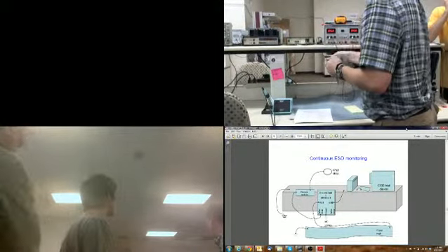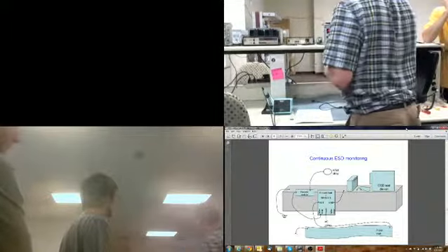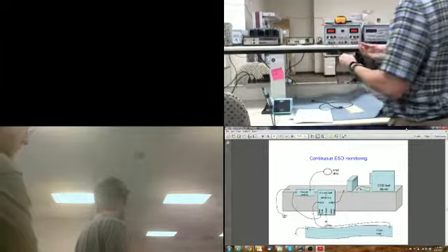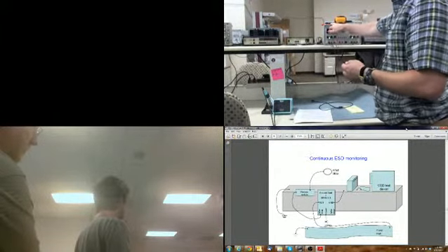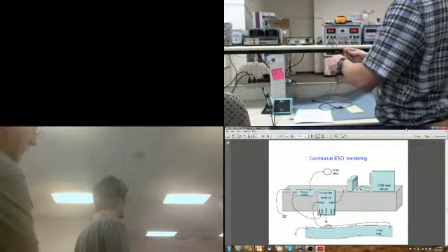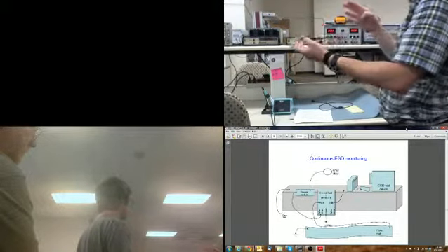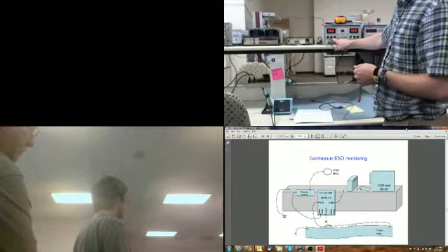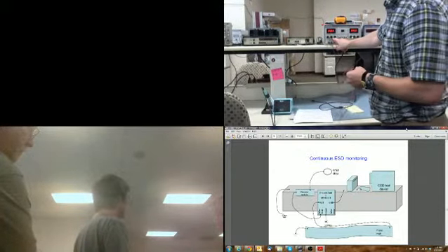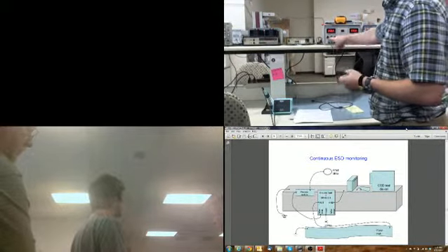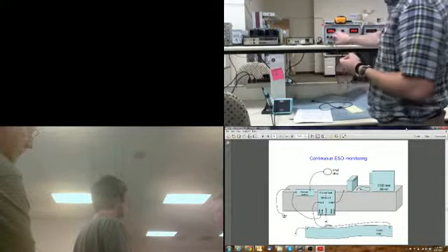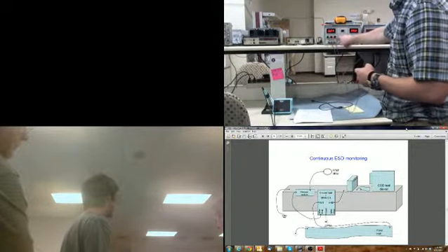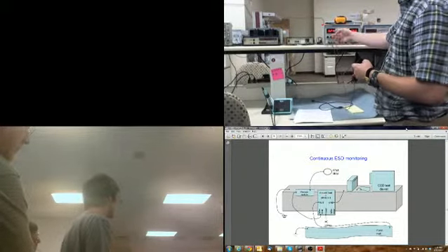Now, let's say I want to current limit this. What's going to happen if this is a current limiting supply? A battery, you couldn't do this to, but with a current limiting supply, I can connect those together. That's created a short circuit. But this light came on. This red light says CC, current control. It's controlled by current right now. Now, I can't see the current. Well, if I push this button, notice that this button right here says V and A. So if you press it, it's going to show you the amperage.